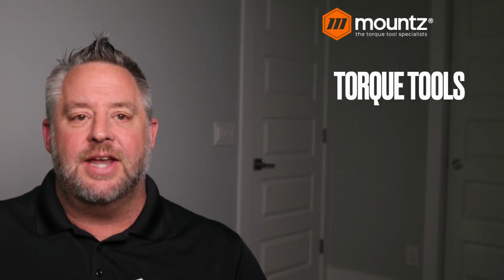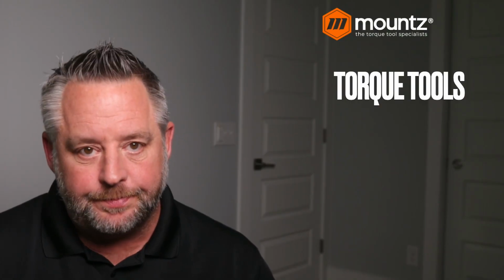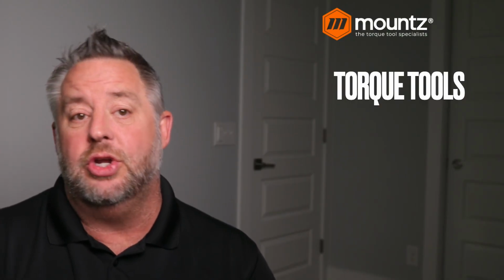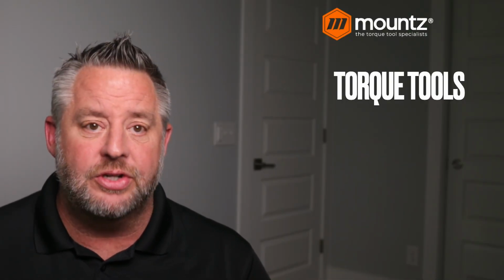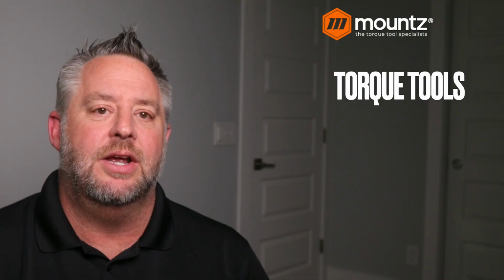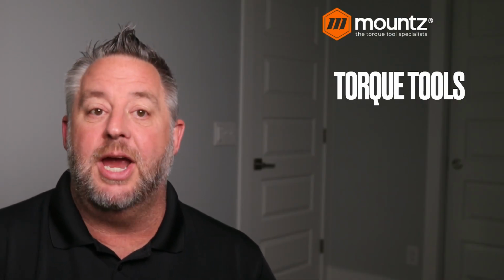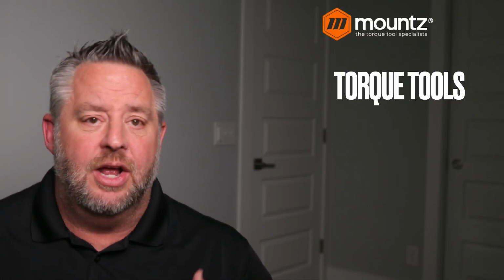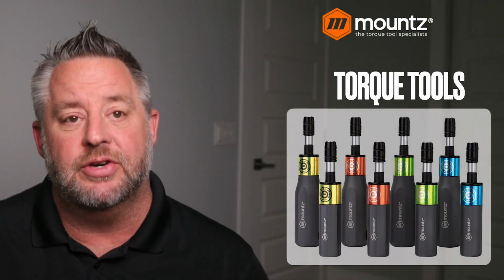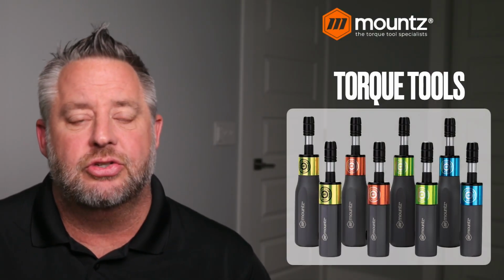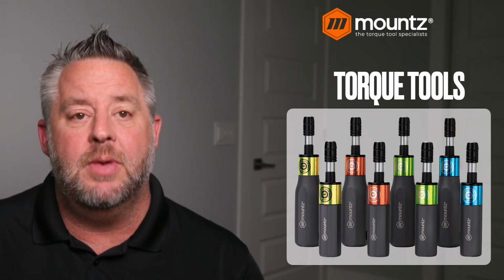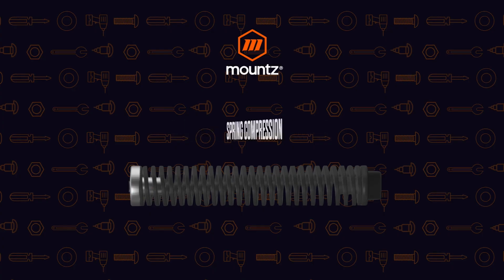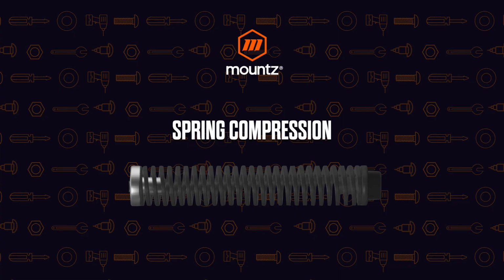So now let's take a look at some torque tools. And not all torque tools will use a lever arm and a force, but we use another way to create a repeatable type of force that we can measure and use. And let's first take a look at torque screwdrivers. Now, the Mountz screwdrivers, nearly 100% of them, all use a spring and spring compression to create a certain torque value for a given output of torque.